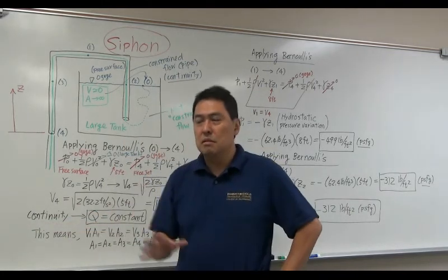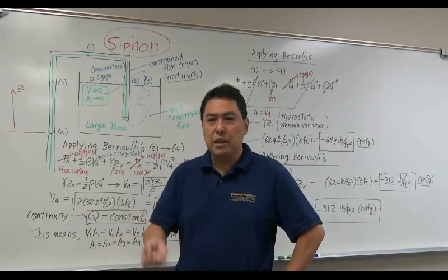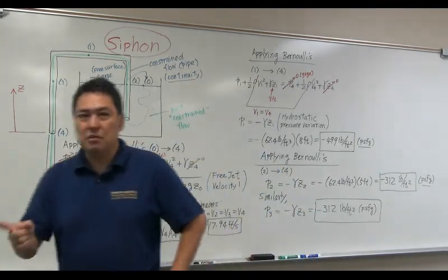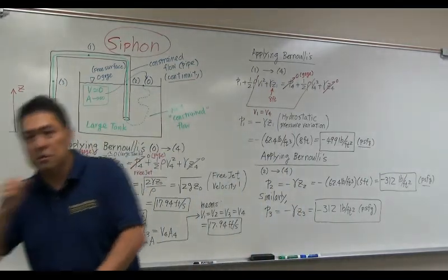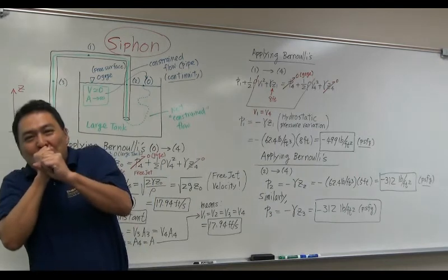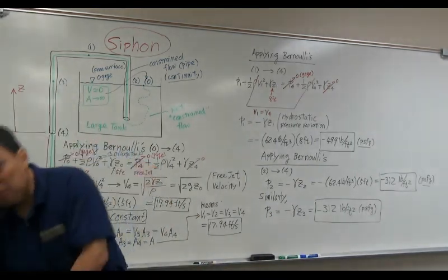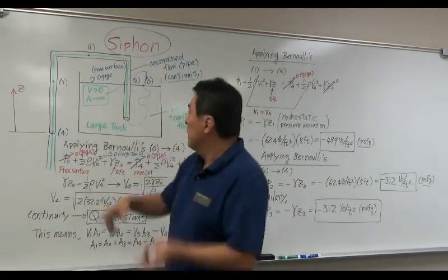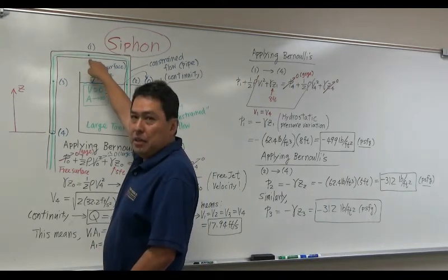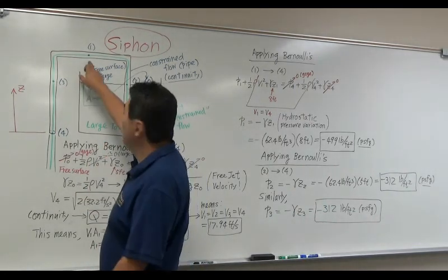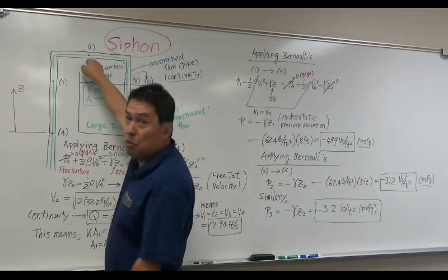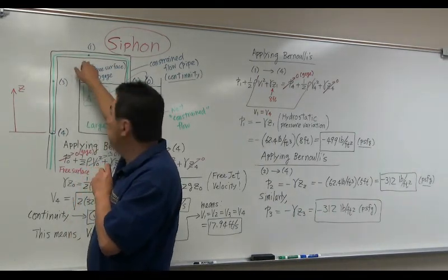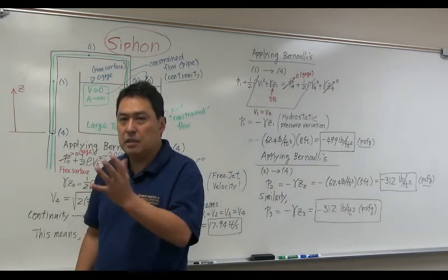Water flows. No, I don't think so. I have to do something to make the water start flowing. Okay, so this is a very classical, actually dumb way to do that. You pick up the other side of the hose and then water comes up and then you remove it. Then you establish the cycle. What you are doing is basically making a suction here by creating lower pressure. So you suck the water in up to this point, then you release it, then the rest of it is essentially the gravitational acceleration takes care of the flow. Okay, and that's the cycle.